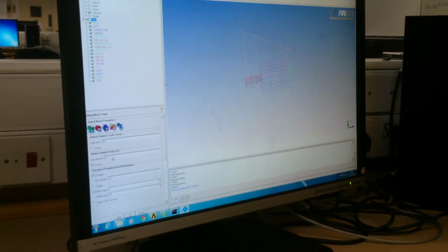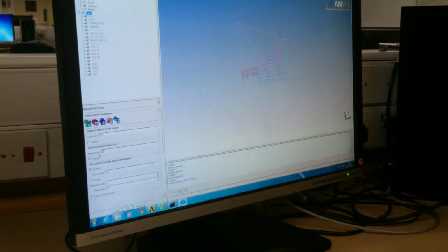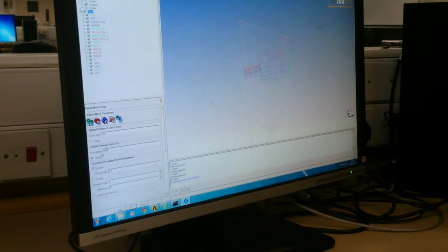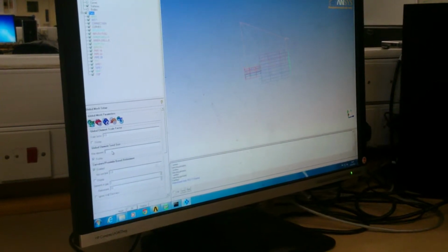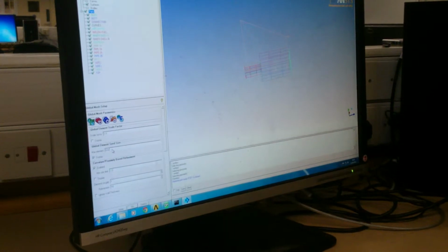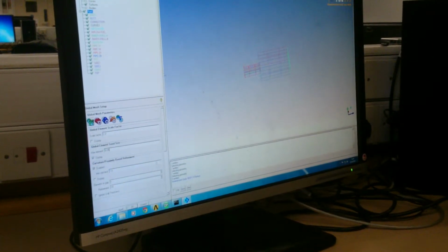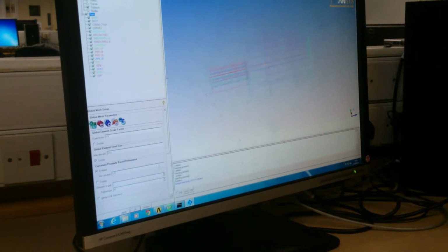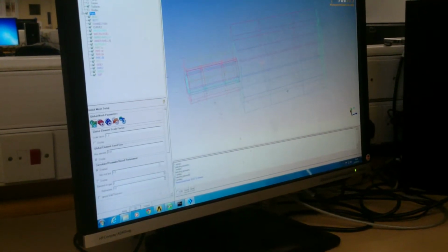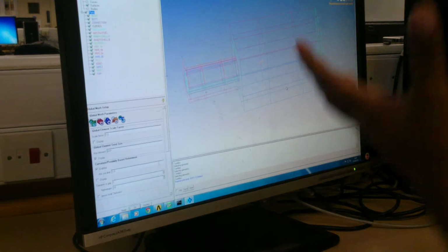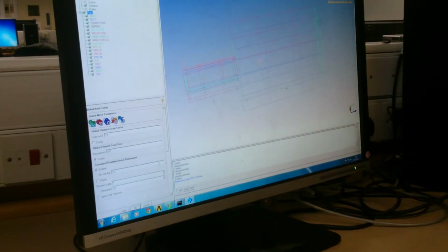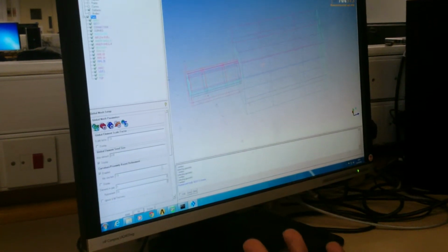Leave the scale as 1, come and make this smaller, 0.1 or 0.01, divide it 100 times. If you say 0.01, say apply. Do you see what happened? It will tell you, oh, I'm going to reduce this to this size, which is too much. Now this helps you to build a sense about the element size. I don't want this, I will say 0.5.